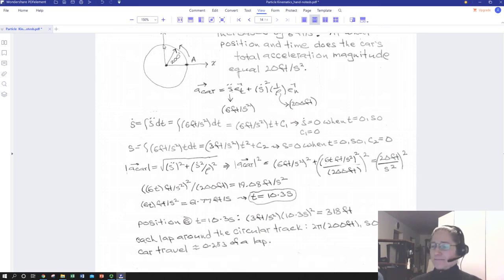So that's just real simple direct substitution into our tangent normal expression for acceleration, given some fairly easy starting conditions. We happened to have a constant radius of curvature. We didn't have to. But for a more complex path, we would have had to have some expression for how the radius of curvature changes with time, with some other position, so that we could relate them if we were going down some crazy curvy path.